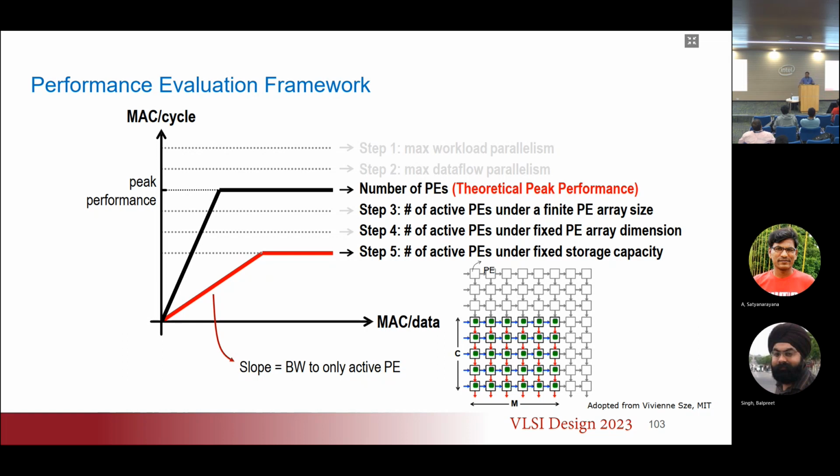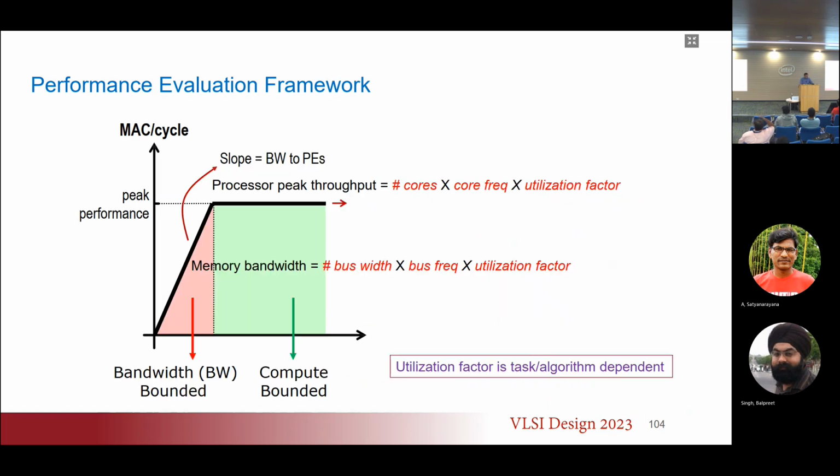They cannot be physically proximal, because if they're proximal, I won't be able to route all these wires. And at the same time, if I put them far apart, then they're going to cause problems too. So either way, I have to think about it. And so I have to think about what is the maximum memory bandwidth I can support, and what is the area cost I can support while making these decisions. And that's at the heart of this.